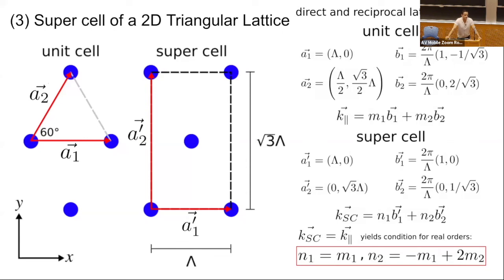Yeah. So as Stephen said, we can implement this ourselves. It's just another mode overlap integral. You just compute the spherical wavefronts manually, and then compute the overlap integral with the DFT fields from the DFT monitor.